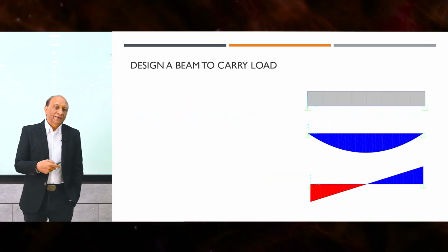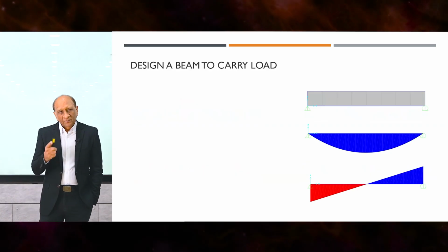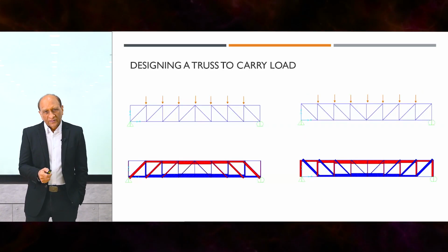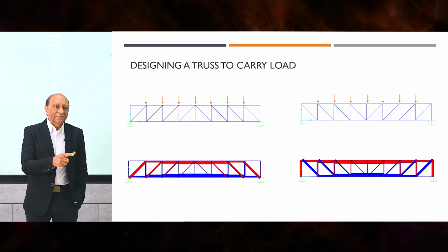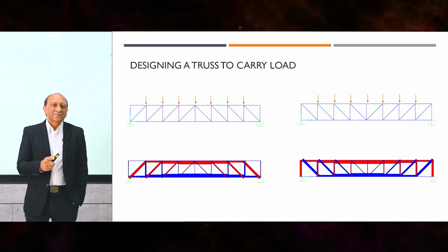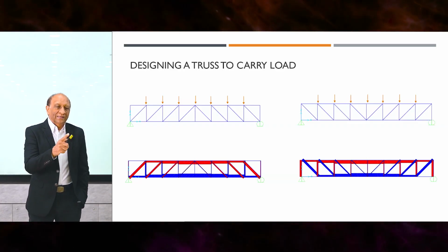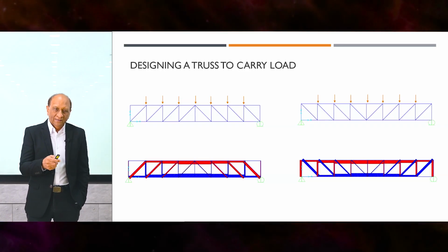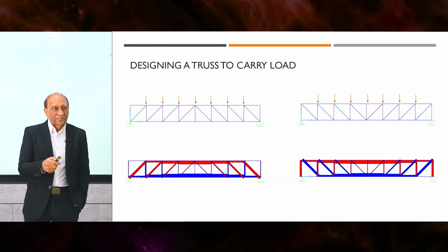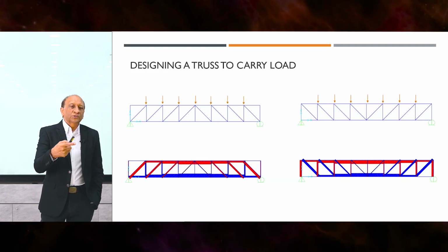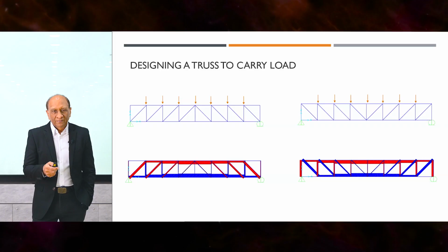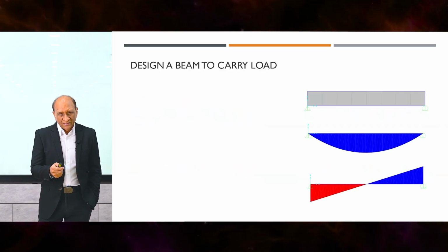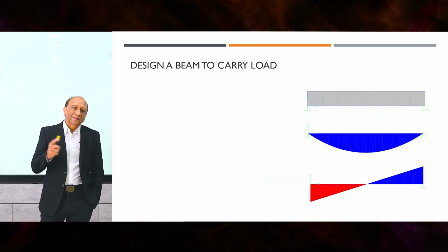Now let's get back to the beam. So if that's a beam, now the thing is that when you design the truss, for example, here, it's very simple. You apply the load using simple statics or calculation. You can calculate the forces in the diagonals, also in the top and bottom chord. We all have done it in undergraduate using whatever method. So directly from the force, you can calculate the size of the member or check the member capacity. But in a beam, we go slightly differently.